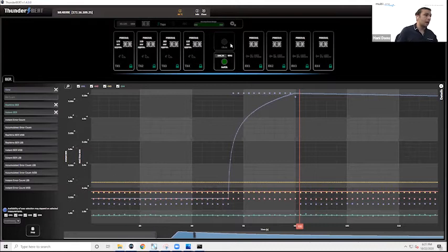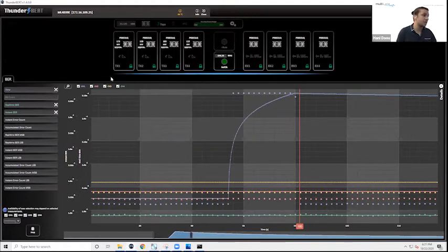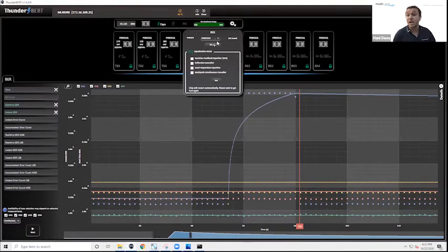So jumping right back into it, we talked about what we can do in terms of tap configuration, error injection on the transmit side. But what we have not talked about are the RX diagnostic capabilities. So right now, I just popped up a pop-up menu of the RX channel. And immediately you'll see, I can go ahead and invert a signal and I will lose lock. I can uninvert it as well, and I will get locked back.